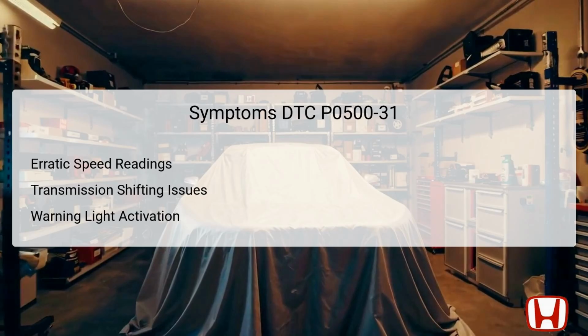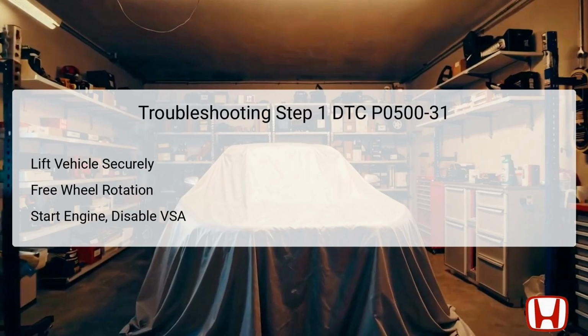These symptoms indicate the necessity of conducting a thorough inspection of the CVT speed sensor, wiring, and TCM for an accurate diagnosis. The first troubleshooting step involves raising the vehicle securely, using a lift to ensure safe access to the components that need inspection. It is essential that all four wheels are rotating freely to accurately conduct tests related to vehicle speed.